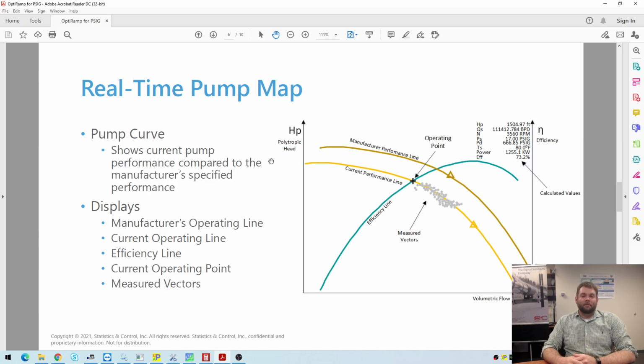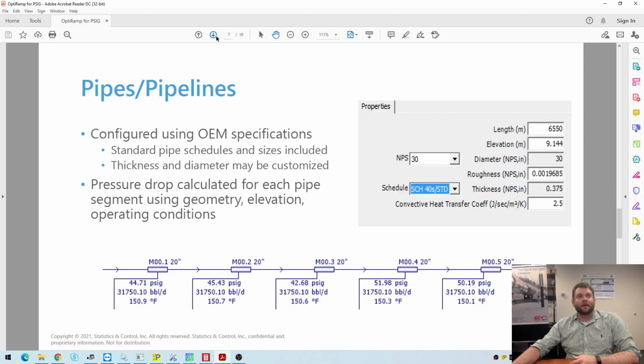And then at other times we can see that they move quite a large amount, whether it be 10%, 20%, and especially when that happens, it's time to either take a look at the pump or do a little bit of maintenance on the pump as well. And so the purpose of the pump curves is just to show how the pump's operating and how efficiently it's operating in that.